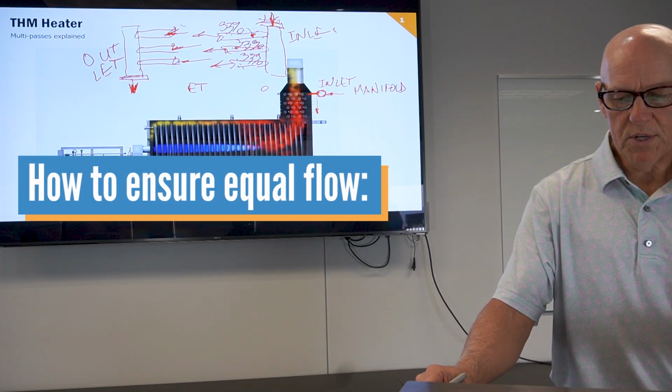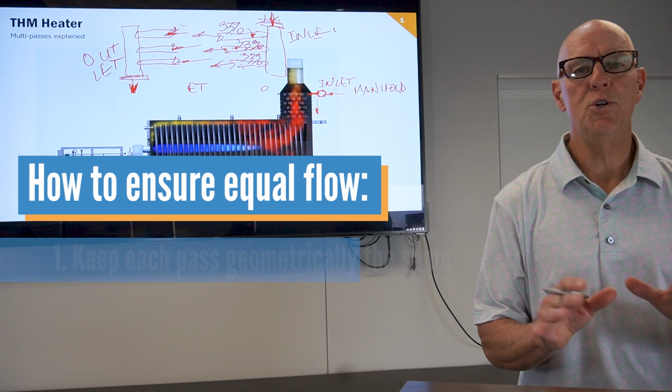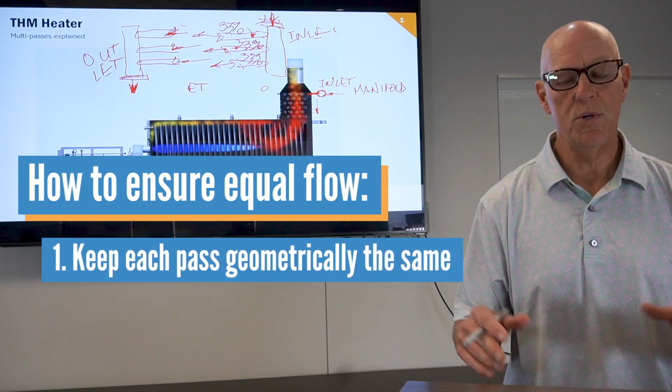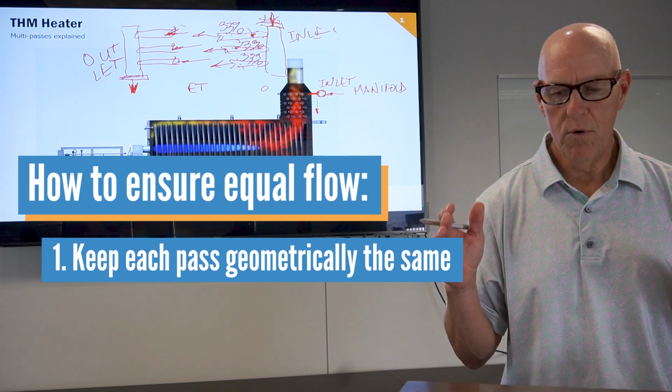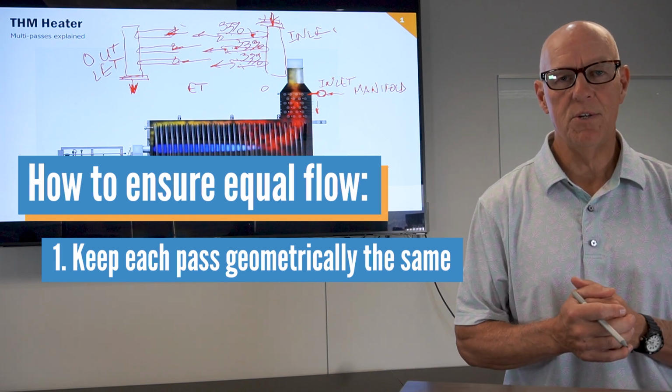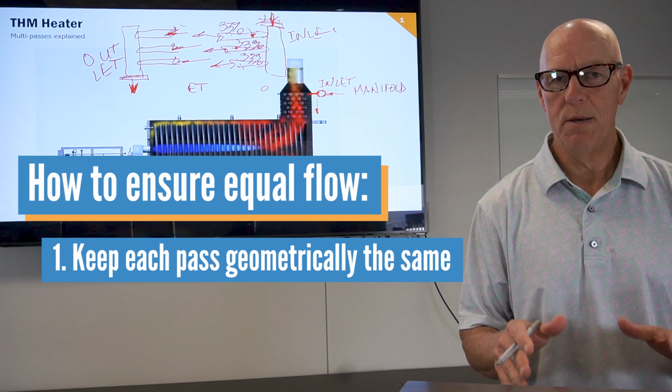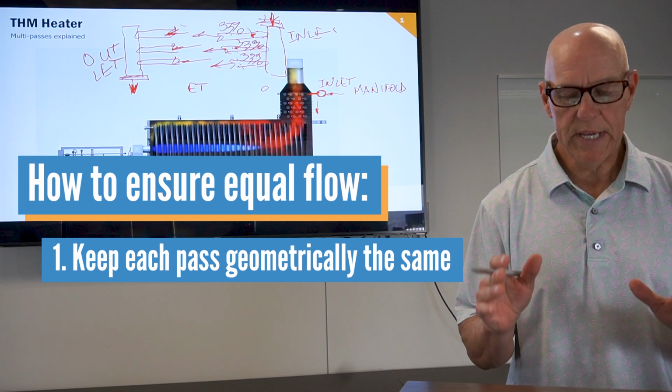There's a couple of different ways to do that. First is you want to make the geometry of each pass the same. You don't want to add extra elbows or extra length of the coil. You want to make every attempt to make that symmetrical in the coil. But that's not a guarantee, because you can't get perfect symmetry, but you can get close.